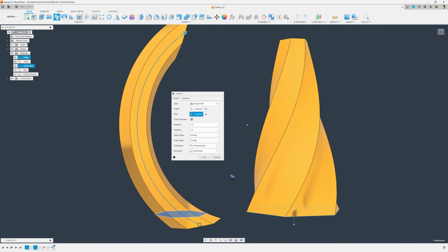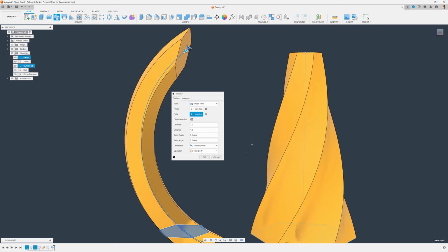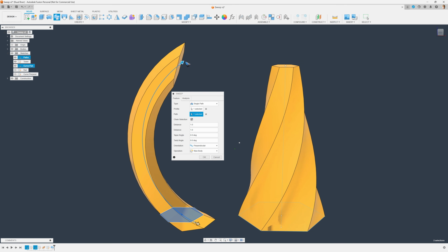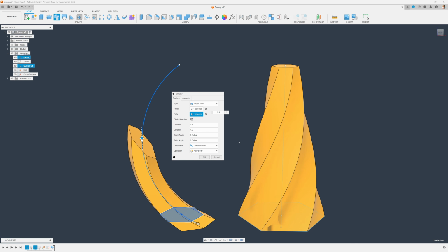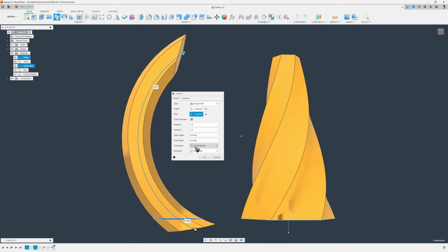Well, what it does is it starts with this, let's say 30-degree angle, and it keeps that 30-degree angle all along that path, which means that here at the top my hexagon is almost more than vertical. If this is what you want, fine, of course, it works perfectly well. More often what you do is make a drawing that is perpendicular to the path that you are going to follow. And we will do that in a minute, but first I'd like to show this orientation drop down.